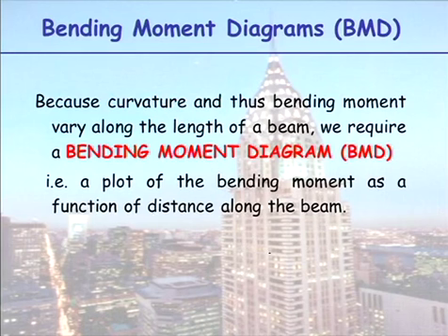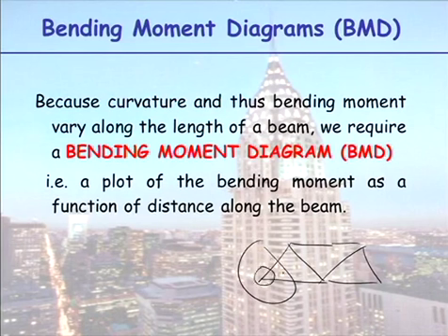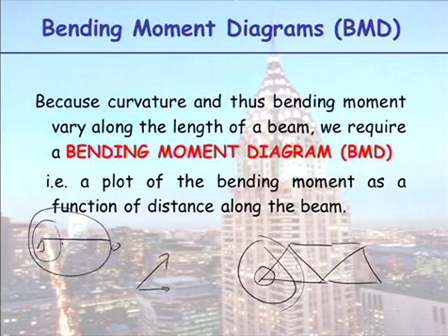It's not constant now. Remember back to trusses. For trusses it was beautiful, because for trusses you wanted to know what a member force was. The member force in this truss is constant compression or tension throughout the length of the member. So in terms of a free body diagram, it doesn't matter if I draw a little one or a big one. When I draw my free body diagram, because my arrows were only axial, it didn't affect it. With my bending moment diagram, if I draw my free body diagram here or here, it affects it because my bending moment varies along the beam.